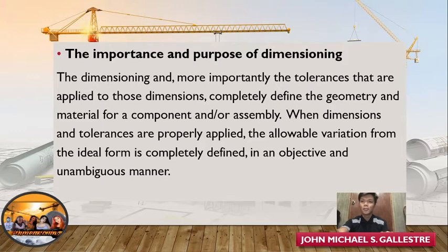When dimension and tolerance are properly applied, the allowable variation from the ideal form is completely defined in an objective and unambiguous manner. Components or assemblies made to this specification should perform in accordance with both the designer's intent and the user's expectations.